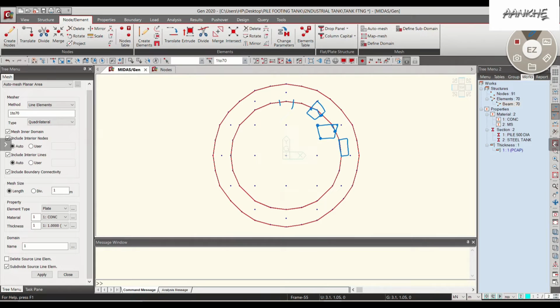It is called P refinement. The more refinement you give, the results become more and more accurate, because it is a numerical method, as you already know from FEM. So the better refinement you do, it will approach a more converged and closer form solution. However, after providing certain refinement, that convergence stops, or the tolerance limit becomes stagnant. So after that we generally leave it, because meshing the plate further will result in nothing. Let us remove it from screen.